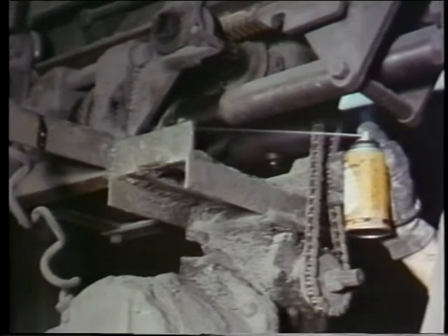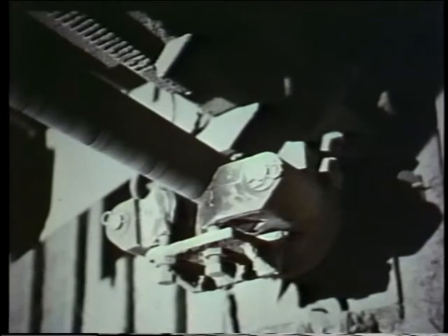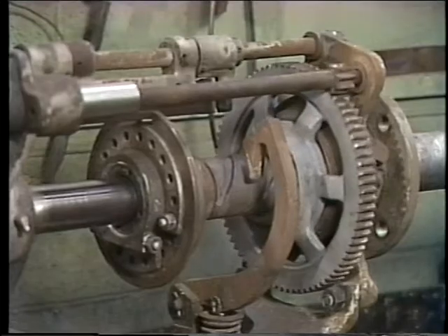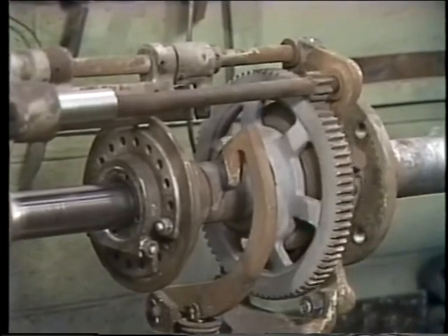Lubrication is an important consideration on rotating stationary soot blowers and on retractables. Lubrication points on soot blowers include lubrication of open chain and sprocket drives and grease nipples for bearings. Long retractable soot blowers have to have the front element support rollers lubricated too. Timing of the blowing cycle is another area that can require attention.